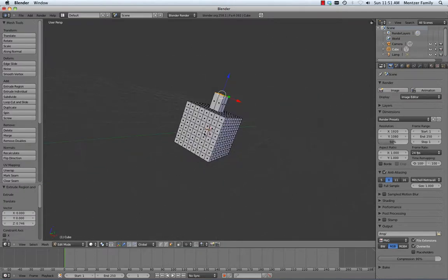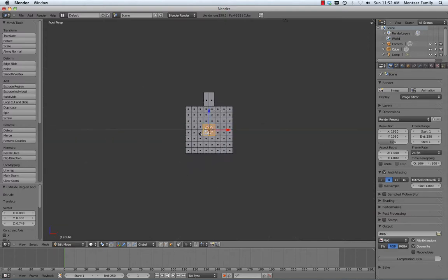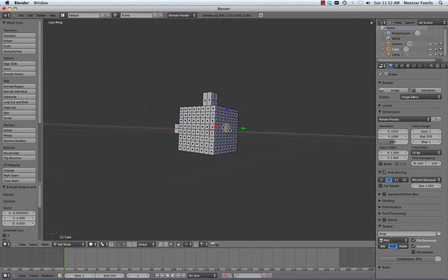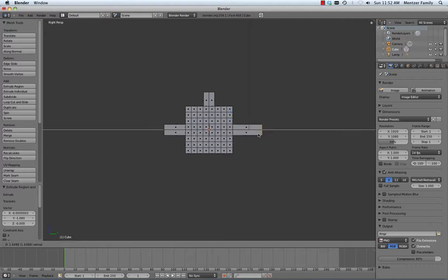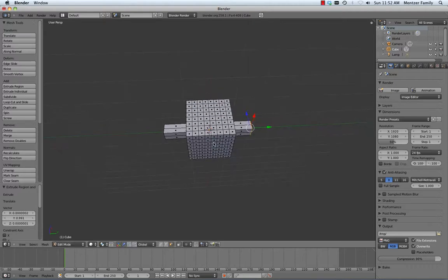And then I can go over and grab, say, these over here, and I can extrude those out to the side to make an arm. And I think for me, I like working in a mode on numpad hitting 1 or 3 so that I'm looking directly on the thing, face on or side on. And I'm going to extrude out now and pull out that arm shape, and then do the same thing over here and grab corresponding faces and flip back and extrude out to make two arms. Now we could do the same thing down here to make a couple legs, for example.